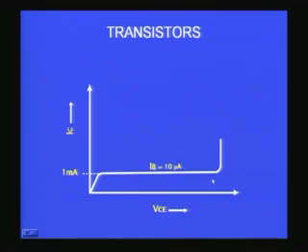And if we go beyond some limit, very large voltage VCC, then you would find it might even break down, and then there will be a very large current flowing without any change in the voltage VCE. So, this is one single characteristic for one single IB value. When you vary VCE or VCC continuously, you get one such graph.